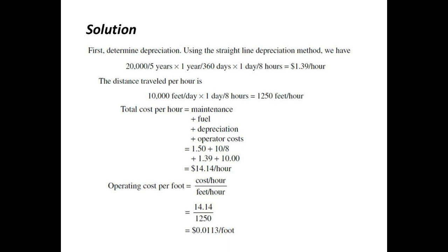The distance traveled is 10,000 feet per day, and in one day we have 8 hours. So dividing that, 1250 feet per hour this truck is traveling. So the total cost per hour is maintenance plus fuel plus depreciation plus operator cost. If we include all of these, 14.14 dollars per hour is the total cost, but we have to calculate the cost per foot.